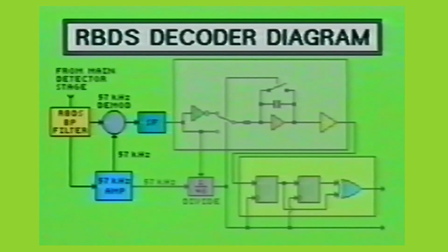You may have noticed that the 57 kHz amplifier stage also passes the amplified signal into a bit rate clock recovery stage. This clock recovery stage also uses the signal from the shaping filter, which aids in maintaining a reference phase lock of the recovered clock signal.